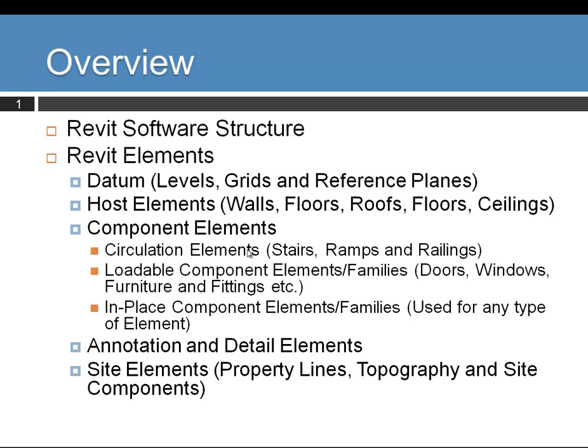Then you have your annotation and detail elements, and I know detail elements represent things you're going to build, but they're often thought of differently because they're typically not 3D. They're basically 2D overlays on top of your 3D elements, and really useful because Revit is a great detailing program. That's one of the things that, when they're marketing the program, they always say is one of the advantages of Revit over programs like ArchiCAD.